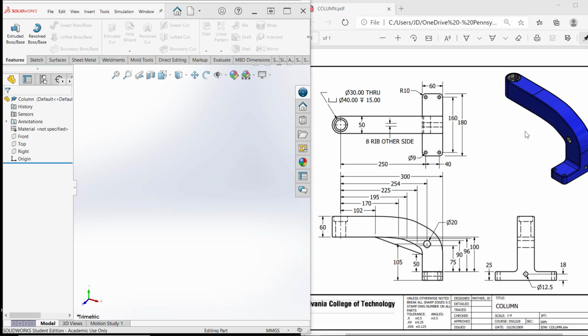So I'm going to do this as multiple separate parts that we can weld together. So I've got this part right here. I think I'm going to do that as a rectangle coming over here. And most of these dimensions are for the spline, so we can ignore most of the dimensions that are on the original drawing. And then I'm going to do this as a rectangle here, and this is a rectangle here, and then I'll put a rib in here, drill our holes, or weld the part up and then drill our holes.